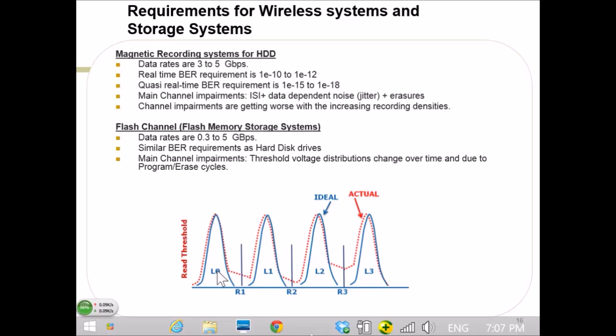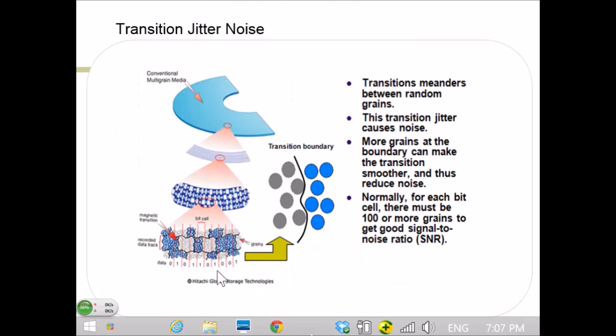Based on my conversation, I would maybe take extra time to explain the source of the ISI in the disk and the type of interference. I would just think maybe a little longer. For example, my understanding is that the flash RAM will deteriorate. Yes, yeah. And you will get more intersymbol interference, the intercell interference later on. Yes, yeah. That is what I've read.